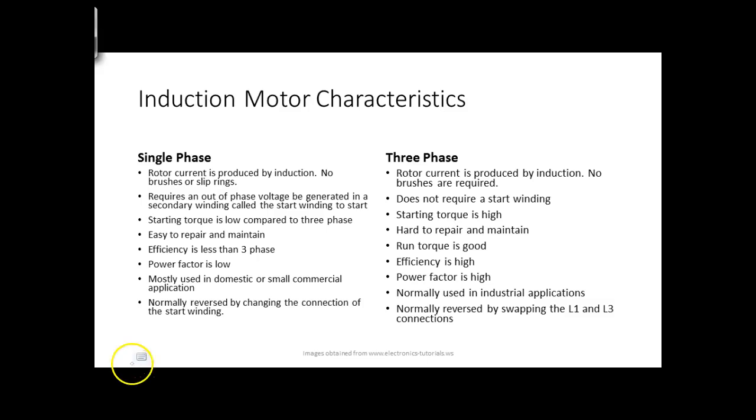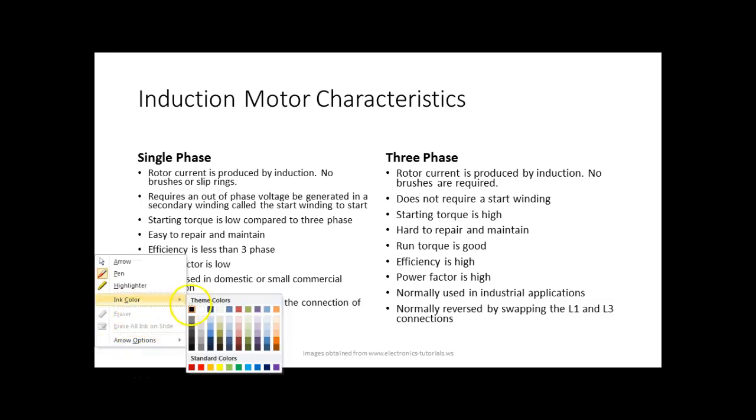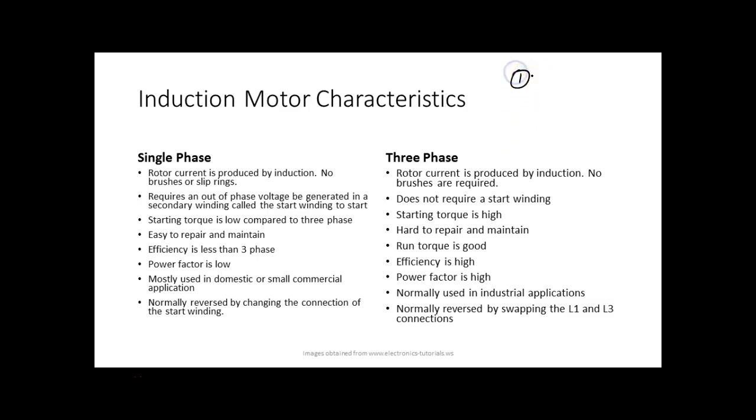And what do we need to do to induce a voltage magnetically? One, we have a magnetic field. Two, we gotta have a conductor. And three, we gotta have what we call relative motion, which means what? I can move the conductor through the magnetic field, or I can leave the conductor stationary and move the magnetic field across the conductor. And what determines the amount?